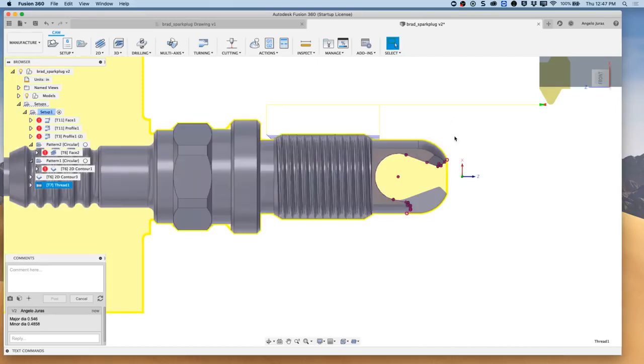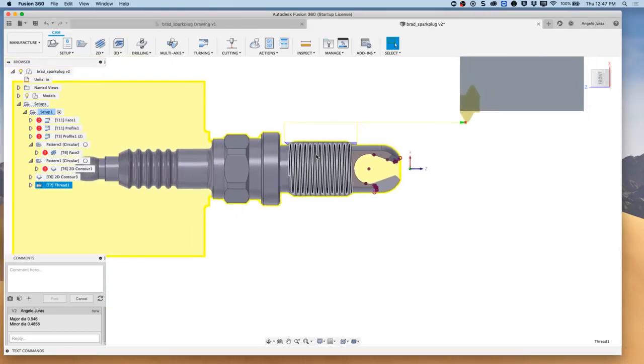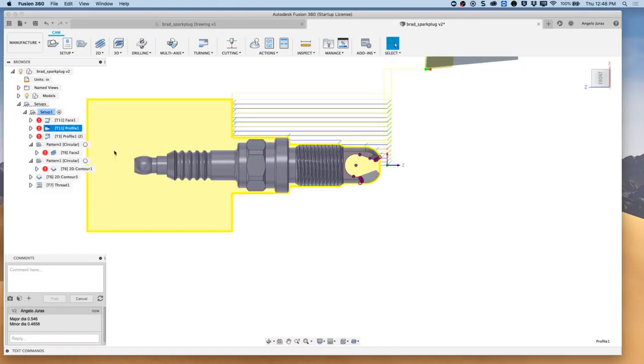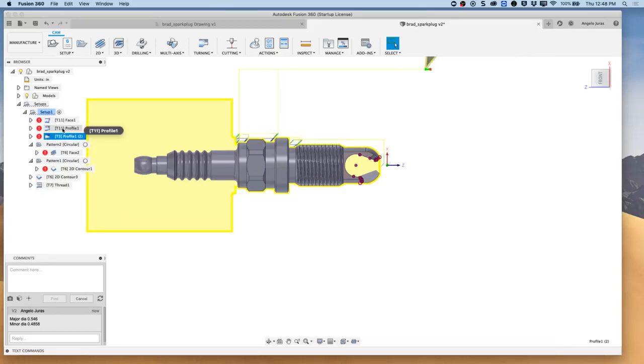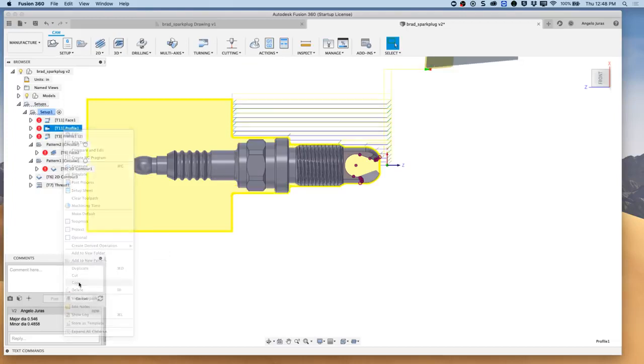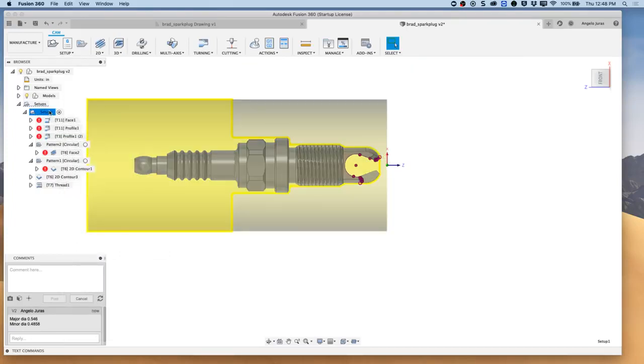I got everything machined thus far up to this point. So what I need to do next is machine the rest of the part all the way here. If you remember, I already machined it using these parameters with this step over and the stock to leave, and then I finished it with that. So I'm just going to copy those two. I'll go here, hit copy, do it one at a time, and paste it.